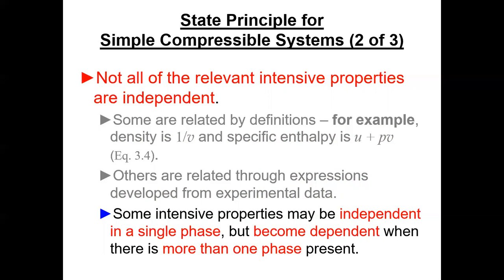If I was to put it into a pressure cooker or a piston cylinder and press down on it with not only the atmosphere, but the weight of the piston, maybe I could maintain it at 100 psi, pounds per square inch absolute. And then it boils, I believe the number is 327. So we can adjust the temperature at which the boiling occurs by adjusting the pressure at which that phase change happens. So you see, during that phase change, pressure and temperature are not independent properties. They are dependent upon each other.